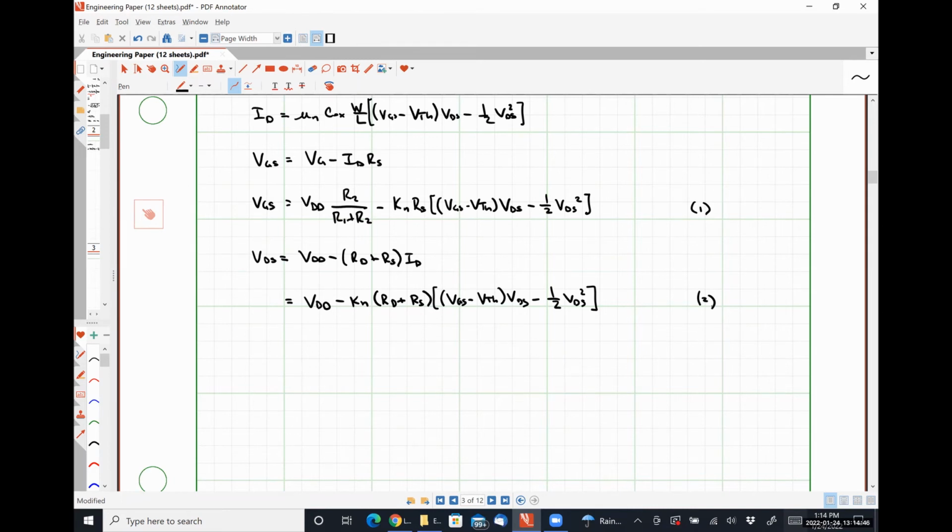So I would argue that your guess value for VDS should be at least VTH lower than your guess value for VGS, since you want the result that gives you triode region operation, right? So we can try to force that by setting up the system where it starts its iterative process in the triode region and hope that it resolves that way over time.